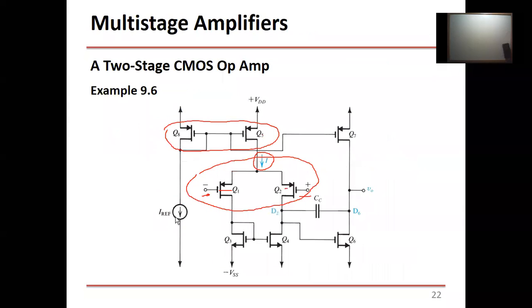Okay, so this is a current mirror. We have an excellent current source here, and we'd like to mirror it here. So I will be the same as IREF, assuming Q8 is matched with Q5.